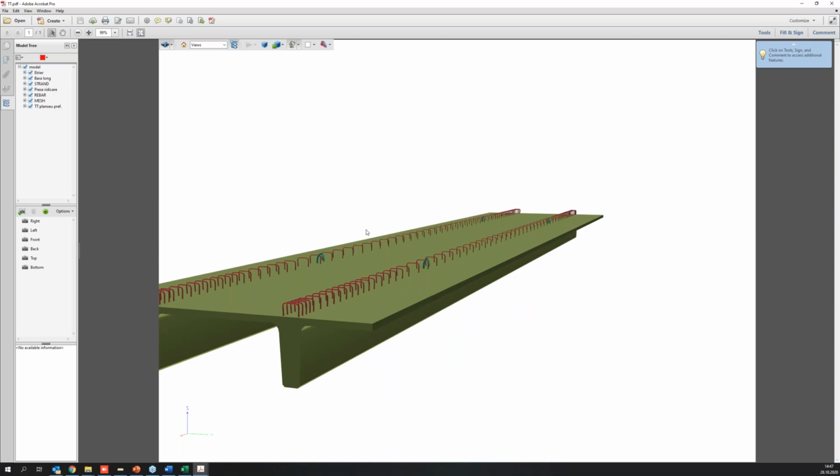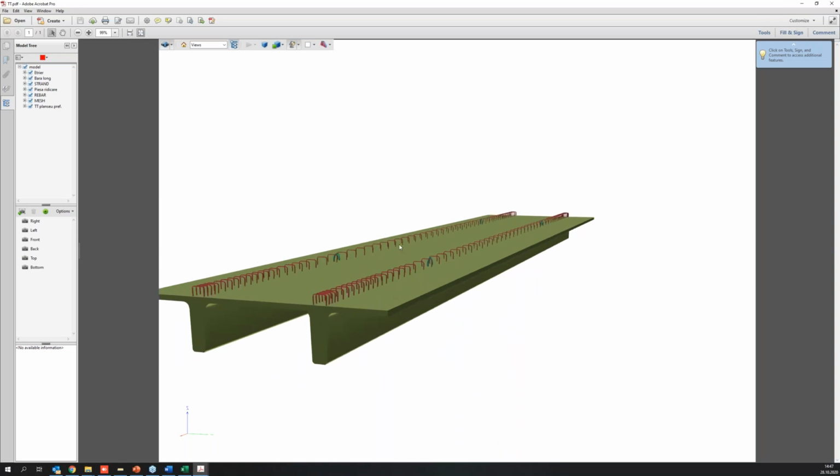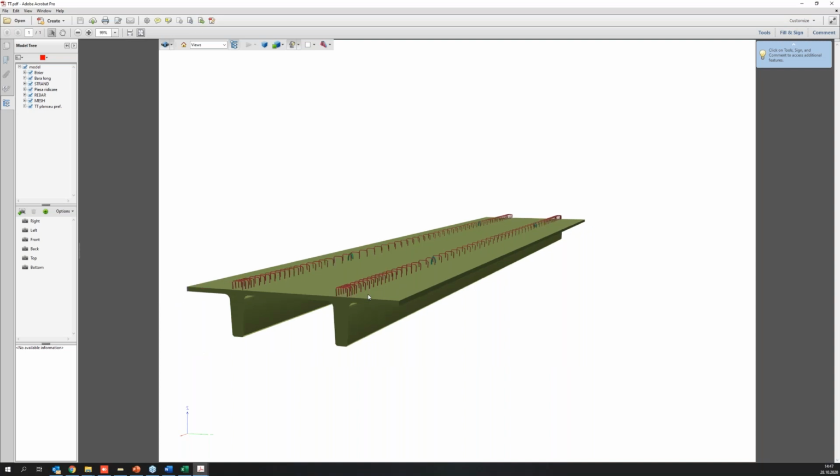A very useful feature in this type of element design is the topping, which you can add or decide not to add if you're doing pre-topping checks. Also, an element to note here is that the thickness of the topping should be introduced with care. Usually these elements have a pre-camber, so the thickness of the topping may not be uniform over the entire length of the element. So the design value needs to be chosen with care.